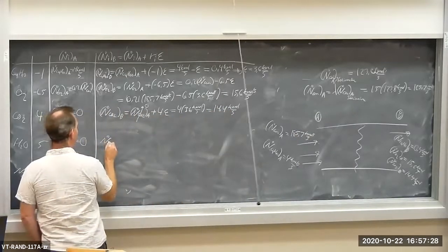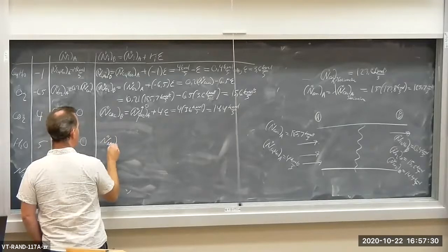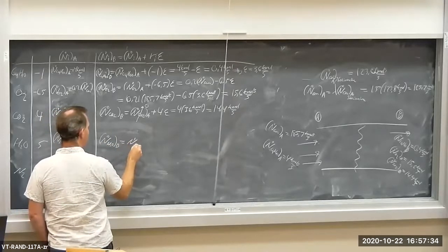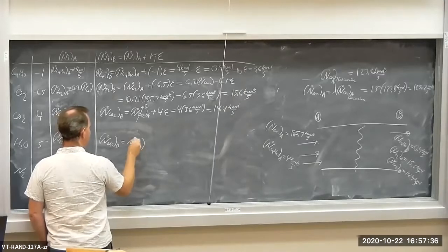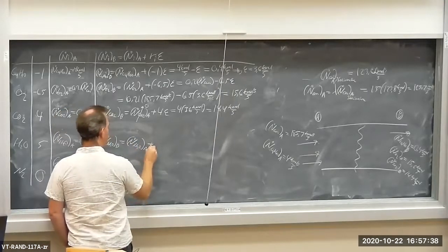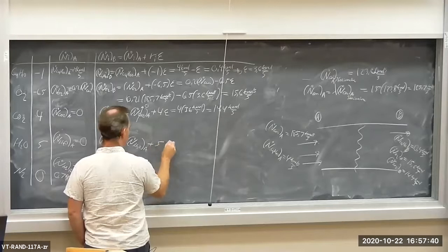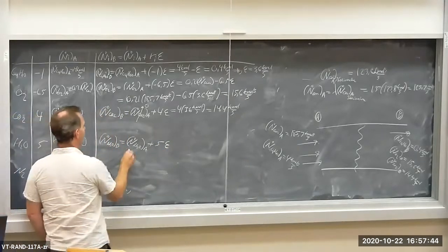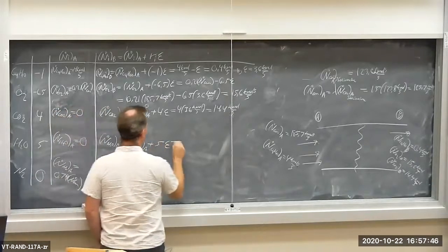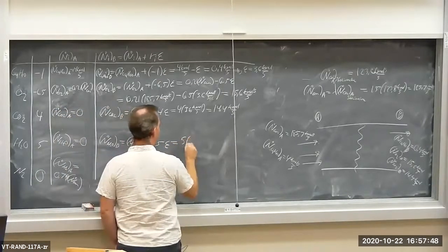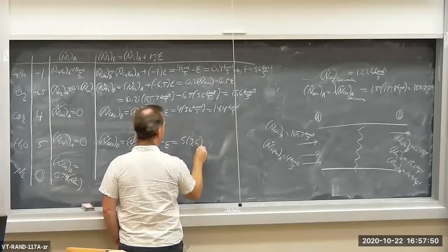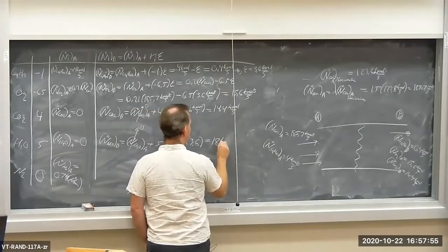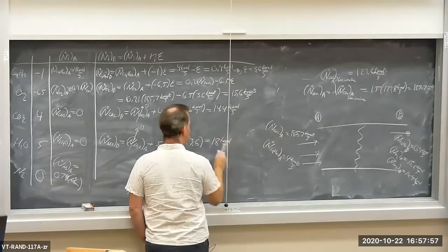The outflow product H2O is equal to the inlet reactant H2O plus the stoichiometric coefficient times the reaction coordinate, epsilon. There is no inflow of H2O, so this is 0. So I have 5 times 3.6, which is 18 kilomoles per second.